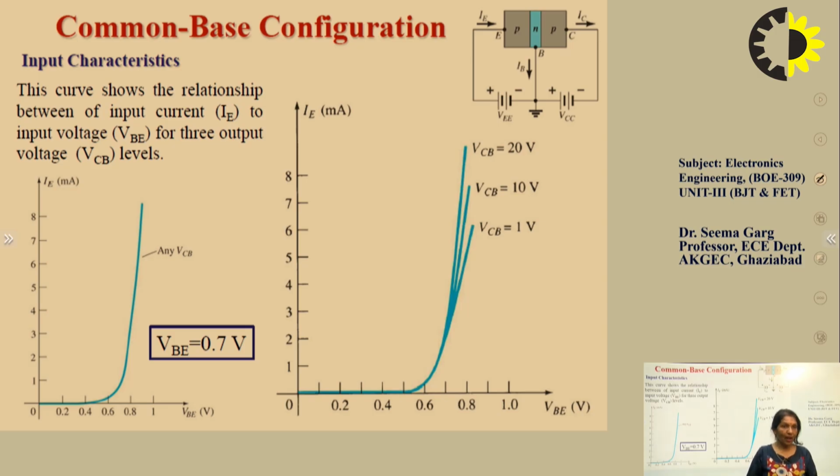So then the question arises that if it is giving a voltage gain of unity, then why is it called an amplifier? Because it is not amplifying any voltage. Then the answer is, it is a current amplifier. It has a high current gain. Also, of the voltage amplifiers, common base and common emitter both have different applications. The common base is used for high frequency signal amplification, and for low frequency signal amplifiers, common emitter is used. So common emitter is the most widely used amplifier in practical applications.